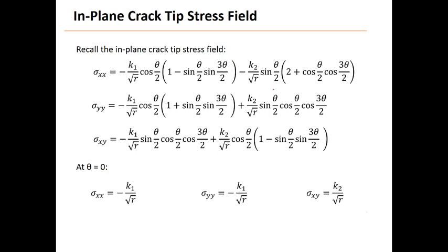Now we are not going to talk about the higher order terms because those are not the focus. So the crack tip stress field really is only an approximation, because we neglected some terms. This is not the full solution, but some significance about this is that the crack tip stress field is universal. That means it doesn't matter what boundary conditions or loading you applied, it's going to look like this. So the form does not change.